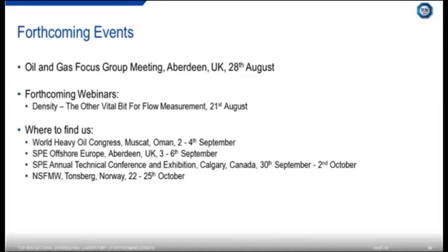Yeah, we've got a couple of questions here. Someone has asked, can you explain the differences in choke flow in a gas versus a liquid? So choke flow, when you're dealing with gas, is actually slightly different. This is where the velocity of your gas is approaching sonic conditions, so it's approaching the speed of sound, and this basically means you can get no further increases in flow rate by decreasing the downstream pressure for a fixed upstream pressure and temperature. So it's a bit confusing because choke flow in liquid and choke flow in gas actually mean different things. A better term for liquid choke flow is probably limiting flow, but that's what it means when you're dealing with a gas system.